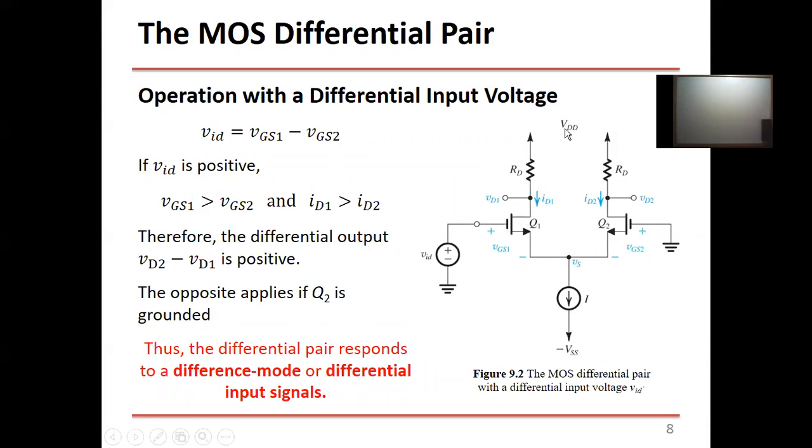So we can consider the DC bias or the DC current in both legs as a common mode signal. So this amplifier will reject this DC at the output even without a coupling capacitor. You don't need a coupling capacitor to link this to the next stage. So this is the first amplification stage, and you already isolated and rejected the DC bias. So you don't need any coupling capacitor.